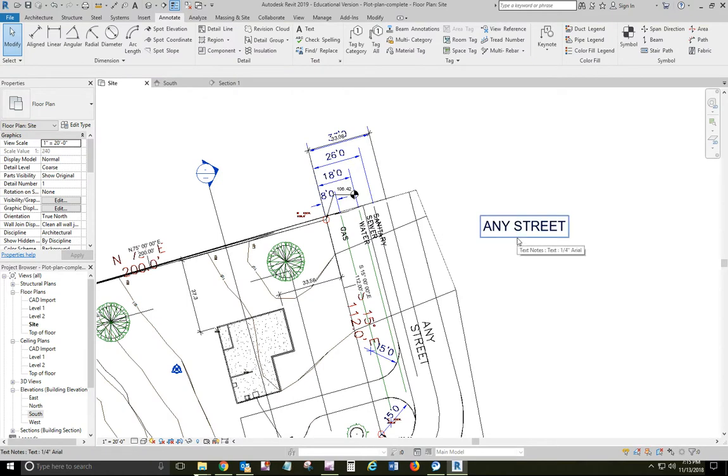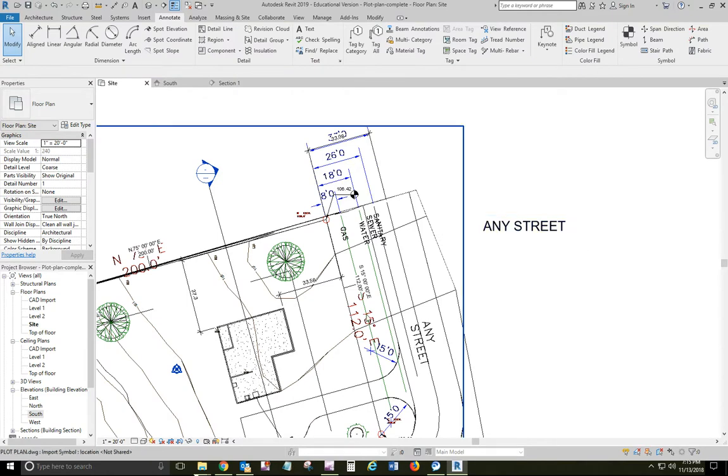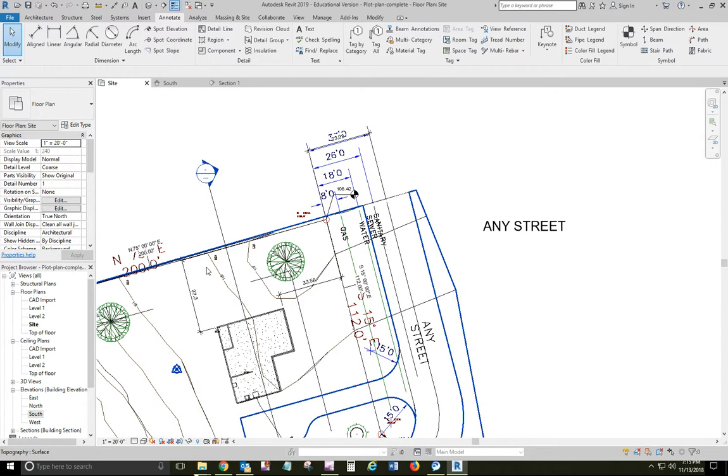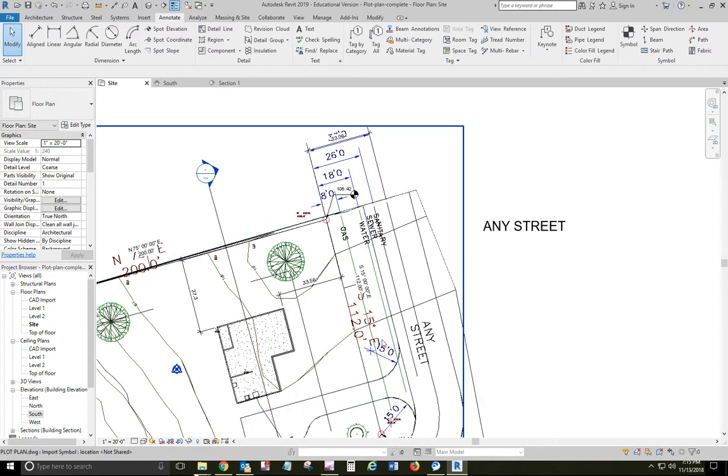Rotating it by hand is kind of difficult. I know the angle of these things. This property line here is north 75 degrees east. So it's like 15 degrees below the horizontal, and this one is perpendicular to that. So this one here was south 15 degrees east, so it's 15 degrees over.